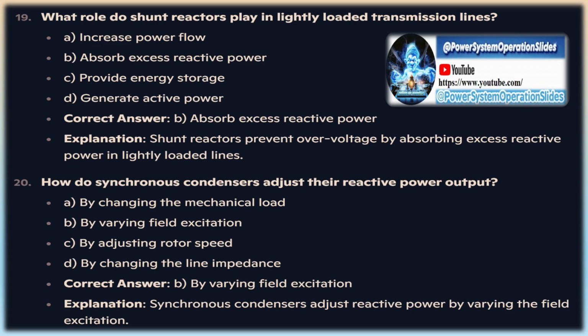Dynamic versus steady-state control: synchronous condensers offer dynamic reactive power support and contribute to both voltage and frequency stabilization, making them versatile and essential for modern grids with high renewable energy penetration. Shunt reactors primarily provide steady-state voltage control by absorbing reactive power, making them ideal for managing overvoltage conditions in long transmission lines but less effective for dynamic stabilization.